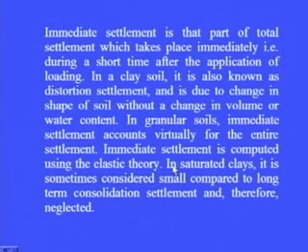Immediate settlement is that part of total settlement which takes place immediately, that is, during a short time after the application of loading. In a clay soil, it is also known as distortion settlement and is due to change in shape of soil without a change in volume or water content.